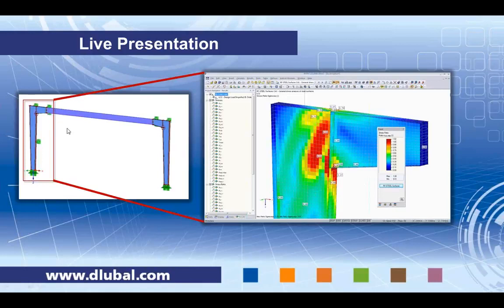In general, you will not find an analytical solution for checking against local buckling of such parts where the bending moment has to be introduced over a corner of a frame into the column. Analytical formulas for plate buckling are available, to my knowledge, only for rectangular plates. If we do not have a rectangular plate, or a certain type of supporting of the rectangular plate, or a certain type of stress introduction into the shear or buckling panel, then it is better to do an analysis within a finite element software.